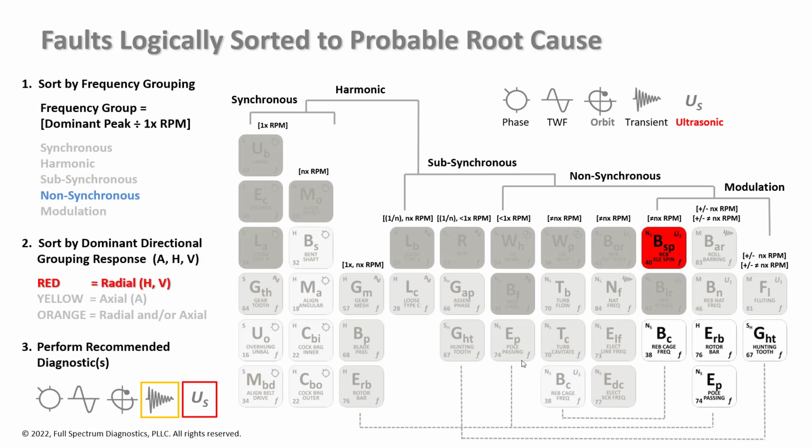So everything else goes away. The only thing left standing is ball spin frequency. It's very likely that fault. Or if there's some other strange occurrence, I don't see it. So it seems pretty straightforward in this case that we have logically sorted to the probable root cause.